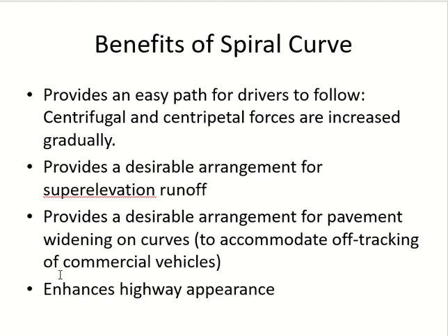Okay. And the last thing is the appearance. It makes the appearance of the curve to the driver more comfortable. Just for the driver. Sometimes you look at the curve and it seems dangerous to you, or it's designed for a speed of 100 kilometers per hour, but the way it looks, it looks dangerous. Just in the morning I was reading that if you have a horizontal curve and a vertical curve at the same location, the horizontal curve can change the appearance of the vertical curve for the driver.